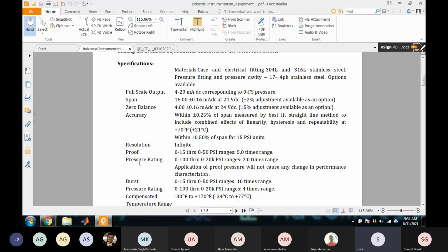Resolution infinite generally means resolution cannot be infinite for anything, because whatever you are measuring with, a voltmeter or otherwise, will have a limiting resolution. In the case of the accelerometer that we saw, there is a noise specification. Noise is random, so when there's an output change, you can never tell whether it occurred due to noise or due to an input change.